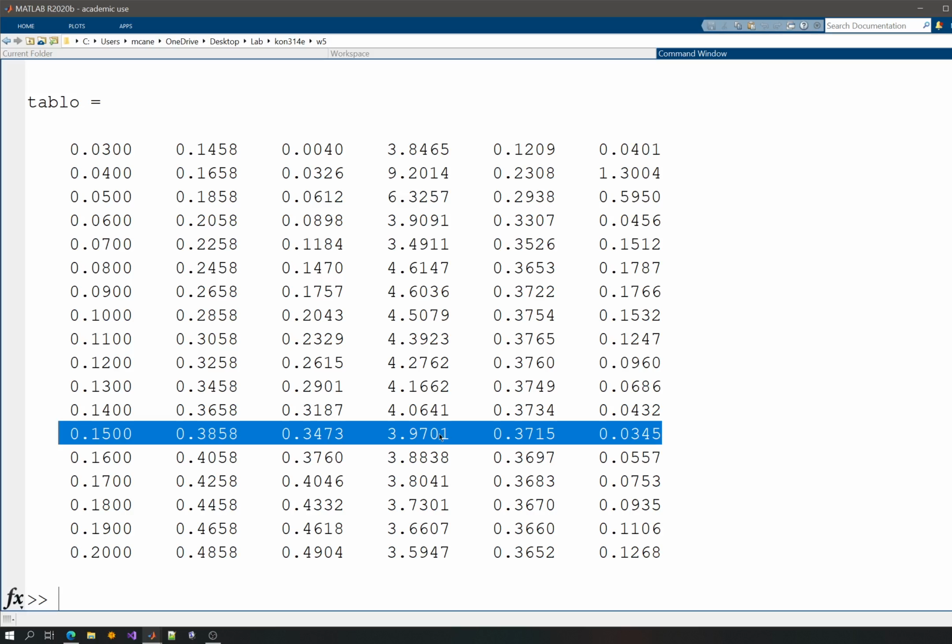This is now the ideal solution, where the settling time is closer to 4. You can see that. Now this is close, but this is closer. So if I want to choose exactly according to the settling time, I can use this combination. But you see that it has a high value of overshoot. So the penalty on overshoot is neglected, sort of.